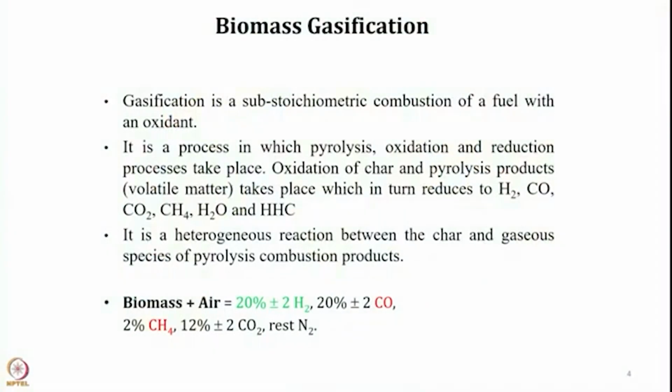Typically gasification, as the name suggests, is the conversion of biomass solid fuel to a gaseous fuel. Gaseous fuel is easy and handy to use, store and transport, unlike biomass, which is a little inconvenient for multiple uses. So, that is the simple reason why gasification is done. Gasification is a substoichiometric combustion of a fuel, so typically we supply less oxygen.